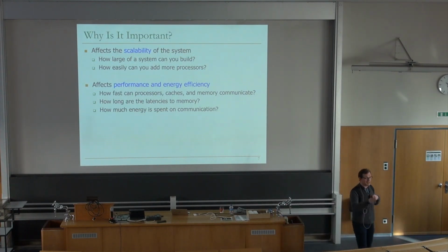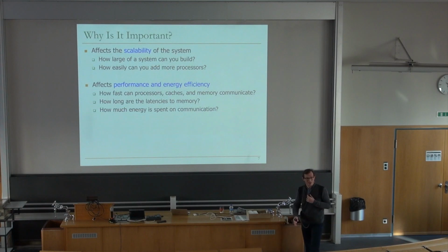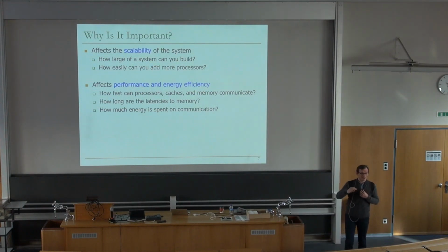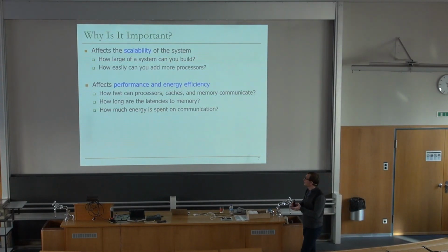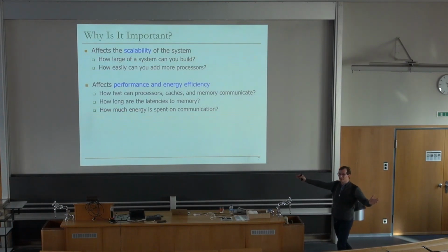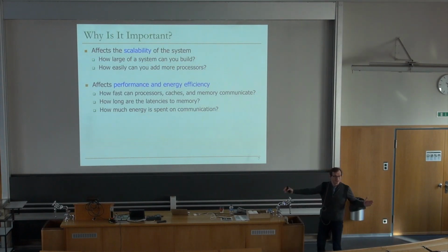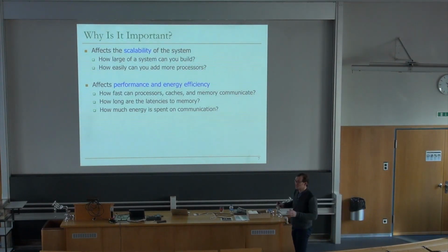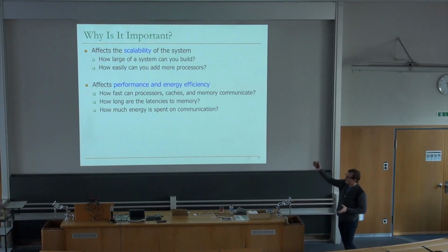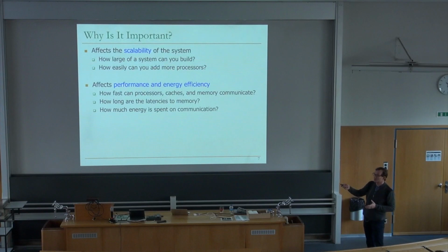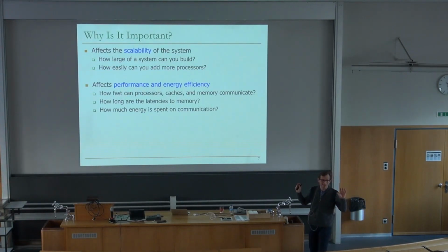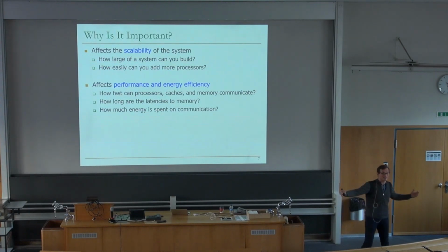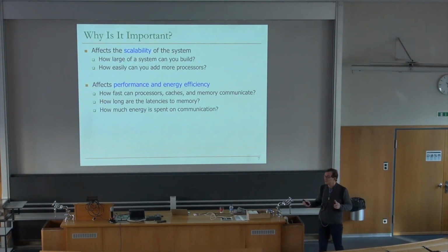If you remember the latency in DRAM, we talked about how interconnect affects that latency. We talked about the idea of tiered latency DRAM, which is essentially chopping the interconnect into two pieces, segmenting the bit lines such that there is a portion that's smaller, shorter, closer to the sensing structures, and that's faster as a result. And there's a portion that's longer and farther away from the sensing structures. As a result, it's slower. So that's an example of a simple interconnect, essentially a bus or a wire, chopped into two pieces, segmented using an isolation transistor. And if you remember, it does affect all of these. It affects performance, it affects energy efficiency, and it also affects scalability. In that case, the scalability was really the capacity of the DRAM chip, right? How big of a DRAM chip you can get given an area constraint.